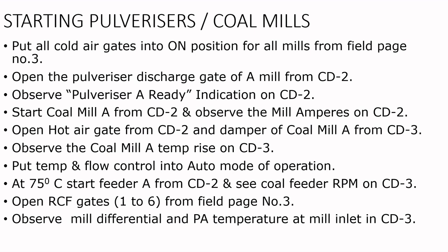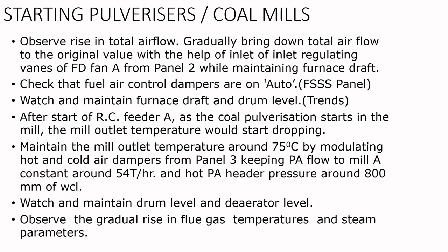Now starting the pulverizers or the coal mills, observe the rise in the total airflow. As you have opened the primary air, there will be rise in the total airflow. So observe the rise in the total airflow.